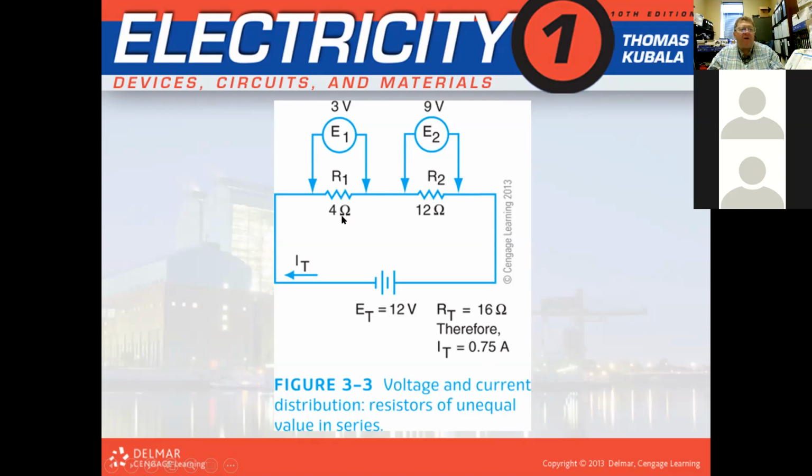Now, to calculate the voltage drop across each one, you take the amps times the resistance, and it's going to give you the voltage drop across each one, because I times R equals E, right? If you don't know what E is, you cover up E. I times R equals E on top.